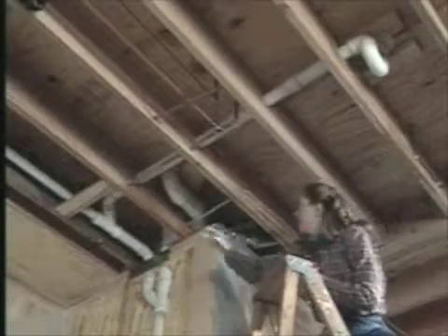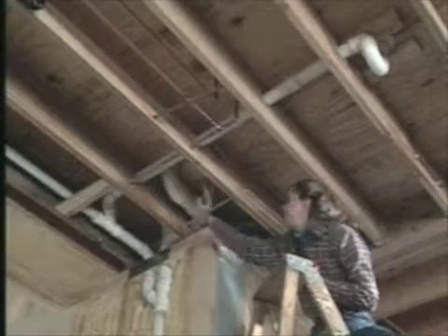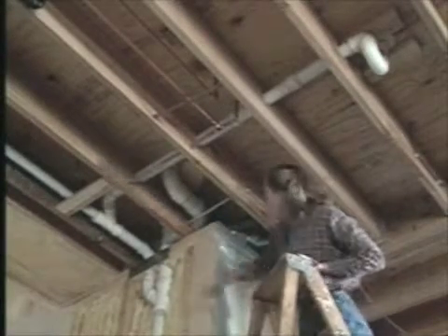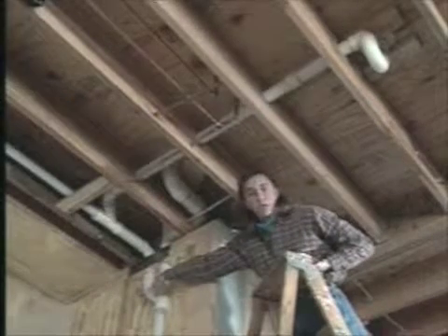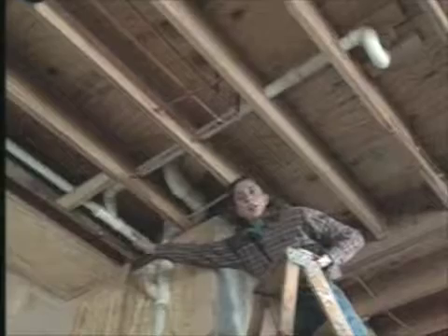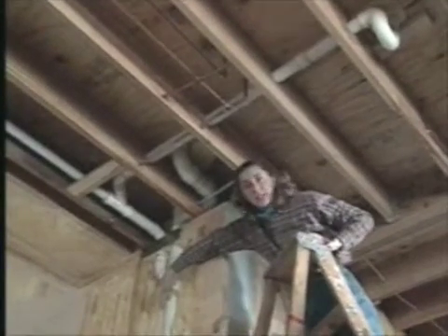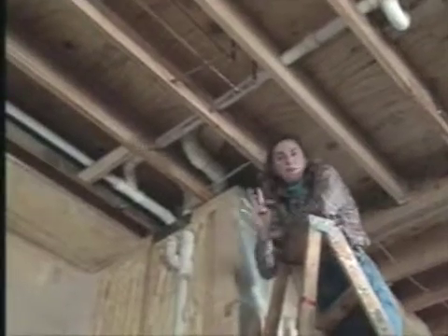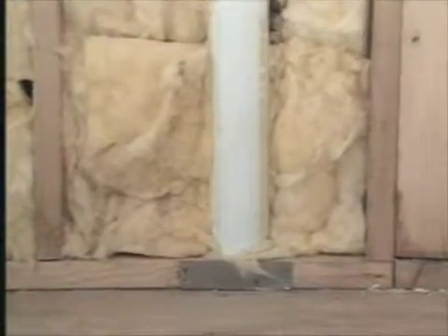Now, the shower and the toilet drains both travel through the ceiling joists, and the toilet drains into this 3-inch pipe, which is called a soil stack, and the shower travels across here where it hooks in with the whirlpool and the vanity drains, which in turn tie into the soil stack. So that means we have 4 different fixtures that are being drained through the soil stack, which goes all the way down the wall, through the floor, and into the basement.